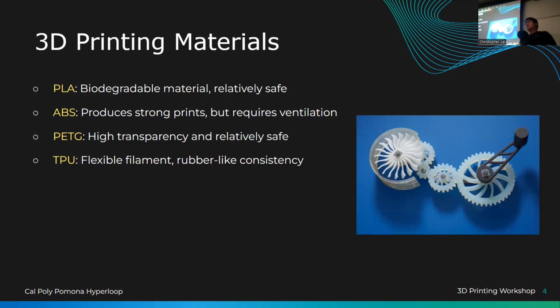A direct drive extruder is when a 3D printer pushes filament out on the gantry itself. The gantry is where the nozzle is. So if you think of when you see a 3D printer and the nozzle moves back and forth, that's where the extruder is. There are two types of printers: one called the Bowden tube printer, where the extruder is to the side of the printer so it has to push the filament a long way until it gets to the nozzle, or you have direct drive, in which the extruder is directly above the nozzle.